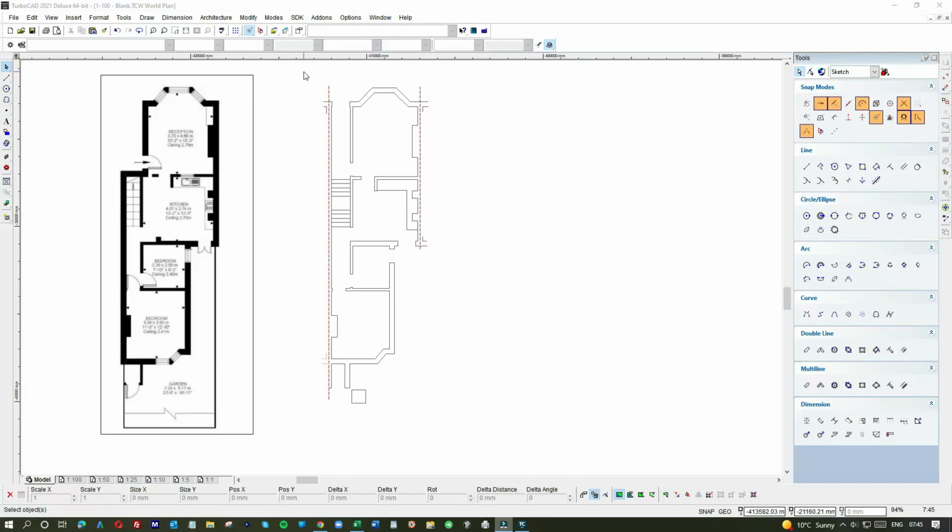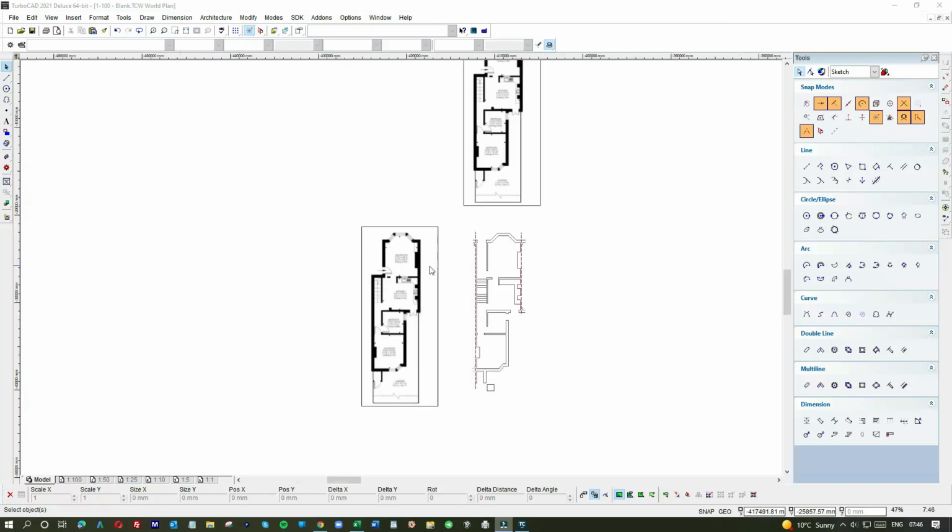Basically the tutorial here was all about how to create drawings from PDFs. Within the tutorial, you've seen me bring the PDF or a photograph of the PDF into the drawing. You've seen me scale the PDF to the appropriate size using the measurements, and you saw I did that 3 or 4 times in fact, to get it right, until we had a photograph that was actually scaled correctly.